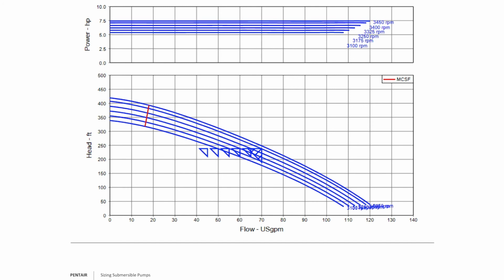Now, in a residential application, would I promise you a big savings? No. But remember, now we're talking irrigation and larger units here. Now, this is a 7.5 horsepower. But if you're running, say, a 200 horsepower system, variable speed curves become very critical, where a lot of customers will see that the investment of a VFD drive will in effect pay for itself when you're using a larger system. But this is a nice way to give the customer a nice diagram. And that's the point of this multi-speed curve right here.